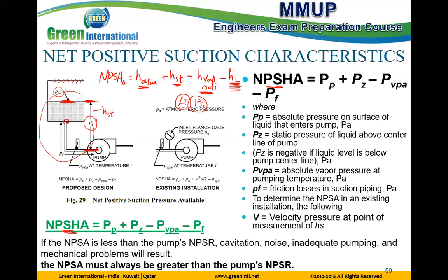a contraction from a large tank to a closed tank, small pipe. Here we have an elbow, for example. Here we have maybe a small pipe to a sudden large area. According to the K factor given, K factor for the elbow, K factor for this one, whatever is given in the exam, calculate with the K factors given. Otherwise, don't think about anything else. Just focus on the given factors like K for this one and so on. Calculate for this, and this is the minor part.